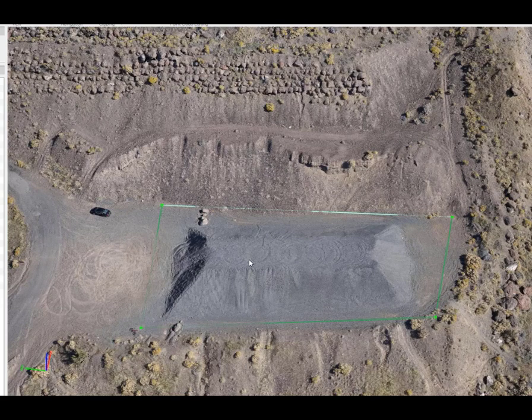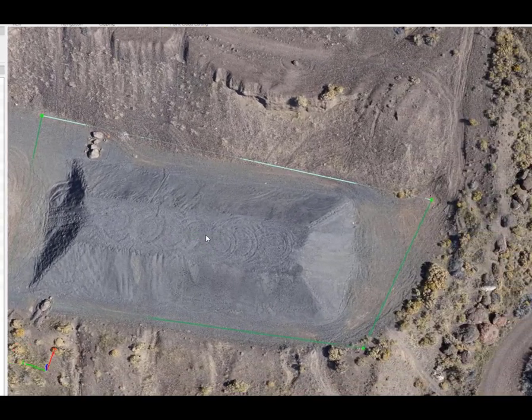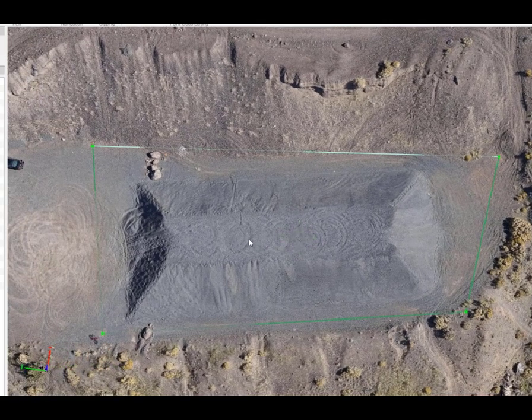And we use them as ground control points, process the data separately, just using no GCPs, but just putting in those 4 points and putting in the known distance as what they call a scale constraint, and then we'll compare volumes and see again if we can get an accurate volume from scale constraints with no 3D GCPs.